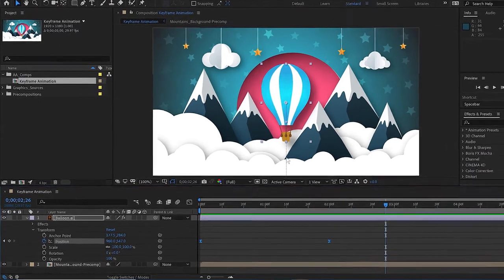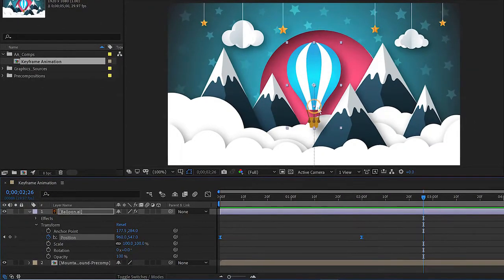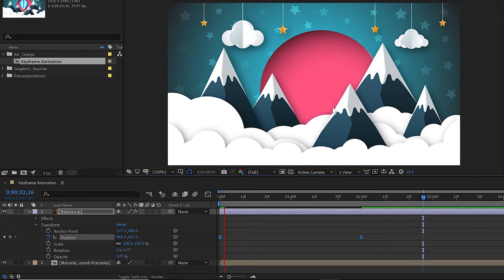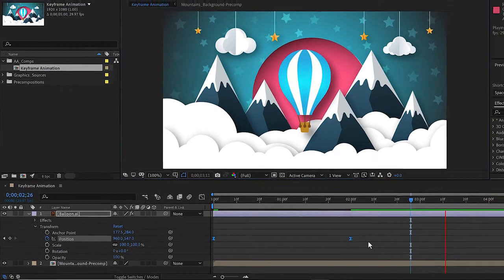Now remember that line? If you look at the line, you'll notice there is a gray circle. If you click and drag on that circle, that will change the angle of the motion path. So I'm going to click and drag to the left so the balloon floats up to the left and then resolves back into this position. Now I'll press the space bar one more time to preview the animation, and you'll see the balloon floats in a different pattern and still resolves nicely because the keyframes are now set to ease.